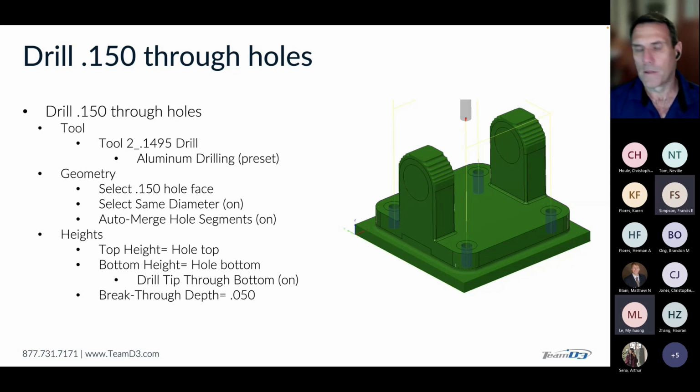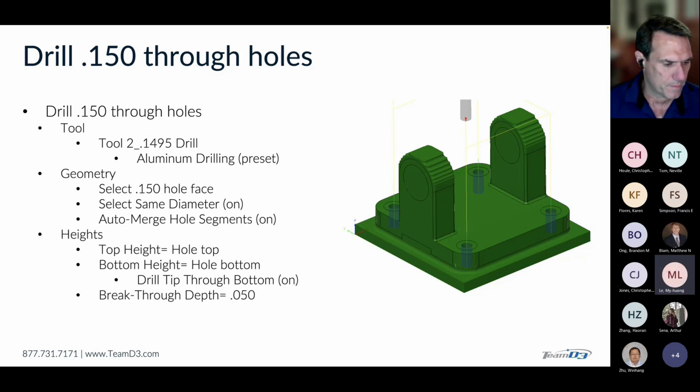So there was one question on whether the drill tools can be migrated over to the milling section or vice versa, since a lot of the tools would be interchangeable. In some cases, yes. For example, you might do a boring operation with a drill, and you also might do a boring operation, as we'll be doing in just a moment, with an end mill. So it's really just how you want to classify it in the library.